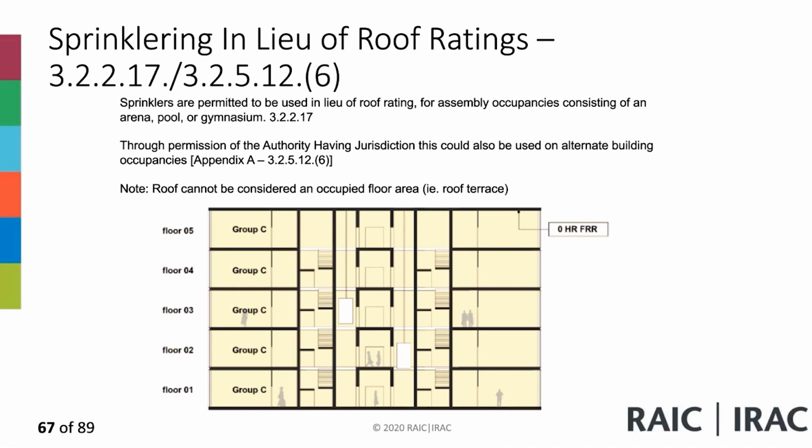Okay, so sprinklers, sprinklering in lieu of fire rating. Some of the articles tell you that you have to rate the roof, especially in non-rated construction. This is in non-sprinklered construction, but if you provide sprinklers, then you can avoid having a rating for your roof, and this is one of the provisions in 32217. You can also apply it through alternative solutions if it's not listed in the article.